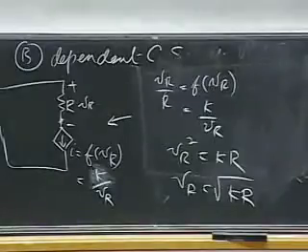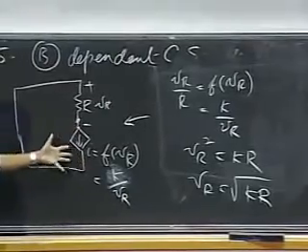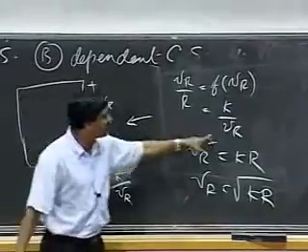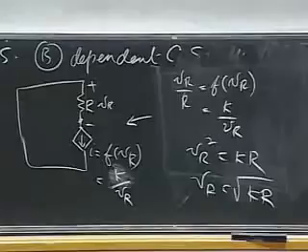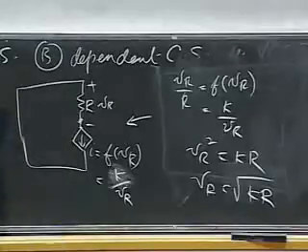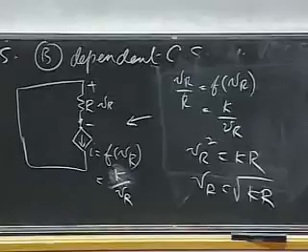Okay, I've gone ahead and applied the node method to this. And when I have to figure out the current here, I simply reflect the fact that it depends on VR, like so, and I just go and solve the circuit. Remember, the workhorse of the circuit industry, the node method. When in doubt, apply it. Okay, it simply works. And notice this is a nonlinear circuit. Okay, the dependence is nonlinear, and I get the response like so.